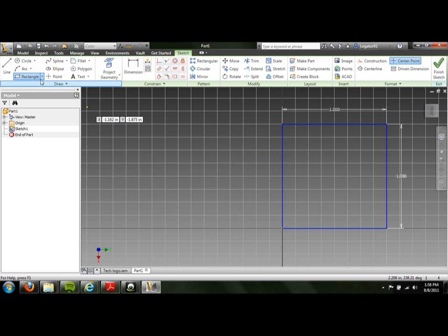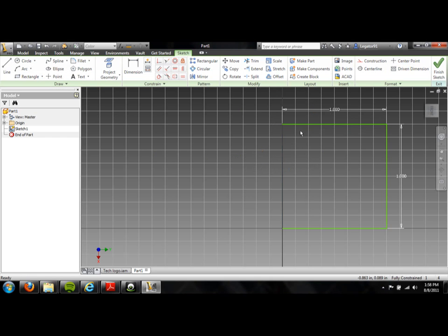Another thing we can do is make a circle. Once again, you just hit escape, and you can delete these lines, and we'll make a circle. Another nice feature is that when you're making different lines for a sketch, Autodesk has built in a tool system so that when you want to center something, it'll center it on the center point of the original sketch. You can already see that line here, and it'll snap right to it. So from there, we can make this circle.